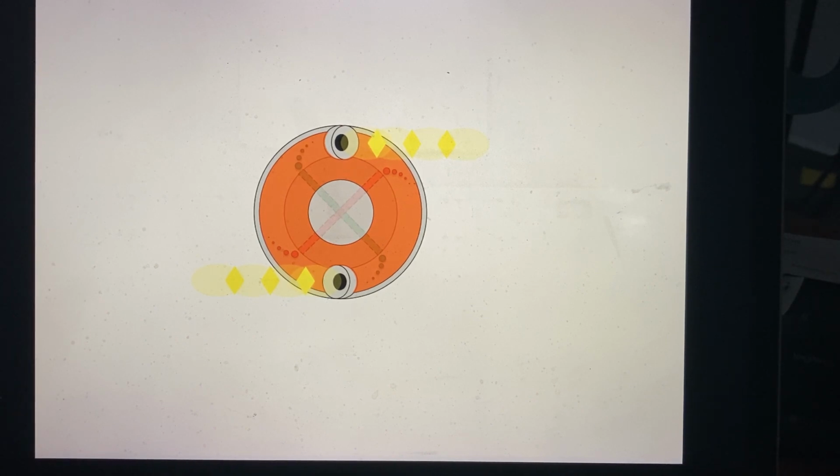The axial component of the exhausting jet velocity is the source of the thrust of the turborocket engine, whereas the tangential component provides the power to pump the propellants through a centrifugal pumping action into the main combustion chamber and imparting rotation to the system. That's the basic operation of the turborocket engine system. While simple, certain aspects of it make its motion somewhat complicated and a little bit counterintuitive to understand.